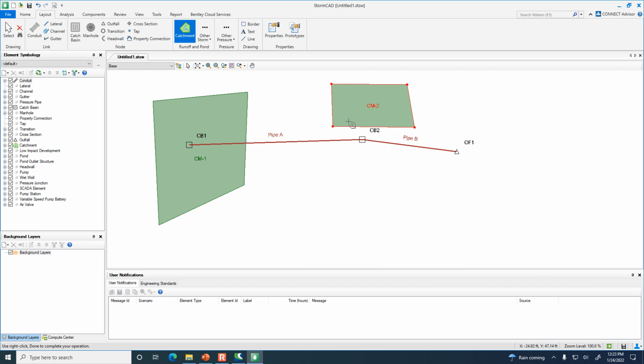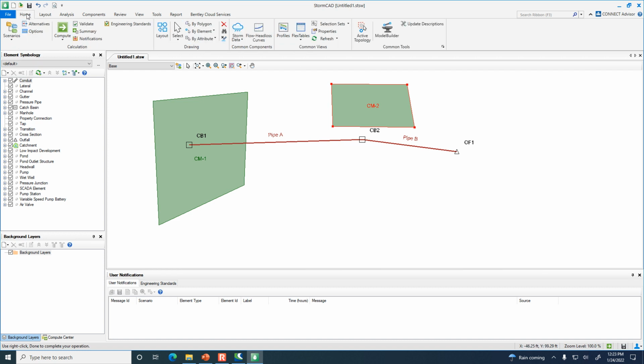So we've drawn the catchments, and now let's go into the flex table for it. Does anybody need help with drawing the catchment? Sometimes that can be tricky because of the right click at the end to make it done. Anybody need a moment? Some assistance? Okay. So assuming that we've got all this drawn up to now, then in the Home tab, in the Flex